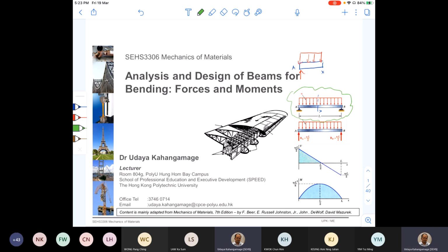I will explain a little bit more later. One is a shear force, denoted by V, and the other one is bending moment, M, two internal resistive loads. The values of this shear force and the bending moment are not constant. They are going to vary along the member A to B.